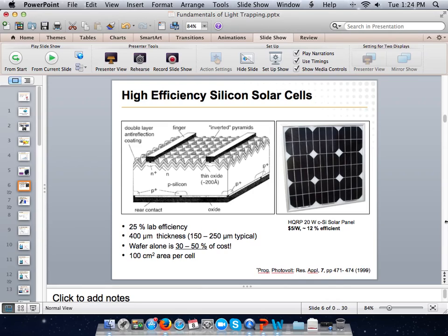You have the light trapping, which is kind of the first step. Then there's what I think they call internal quantum efficiency, IQE. So that says, now that I've trapped the light, how effective am I at converting it to electricity? And then there's the issues, like you say, of, I waste a lot of energy by exciting particles above the band gap. So there's internal issues like that. There's some thermodynamic issues where just the mere virtue of the thing being warm causes you to lose a lot of energy. So all told, you put all that together, and it turns out, 25-30% is kind of the most efficiency you can even possibly get given the constraints.